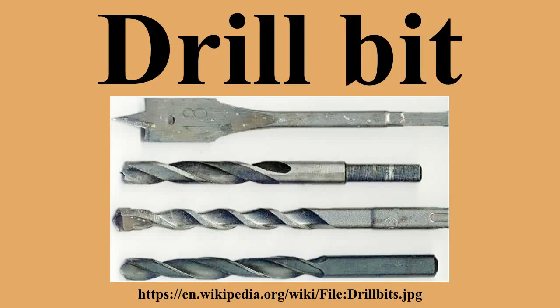Most of these bits are custom-made for each application, which makes them more expensive. Unibit. A unibit is a roughly conical bit with a stair-step profile. Due to its design, a single bit can be used for drilling a wide range of hole sizes. Some bits come to a point and are thus self-starting. The larger size bits have blunt tips and are used for hole enlarging. Unibits are commonly used on sheet metal and in general construction.